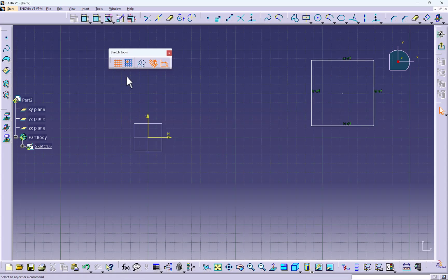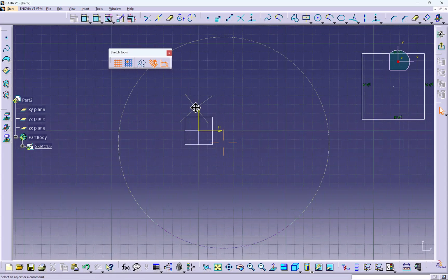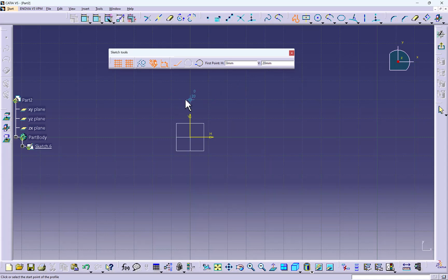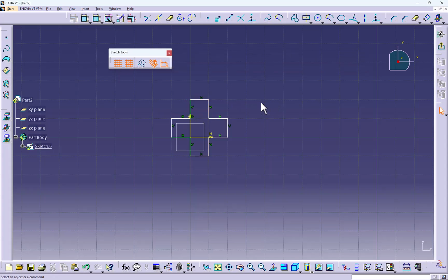We have one grid option. If you have used AutoCAD, you are familiar with the grid tool. You see that grids are enabled. If you want to work with the grids, you can enable the snapping point, and by picking the grid lines, we can draw something. We can see that it's picking grid boxes. I can pick the grid box and draw something exactly. Let me undo with Control Z here. It's taken arc. We'll just draw like this. We can do it by picking the grid boxes. Also, we can draw exactly. Let's turn this off.